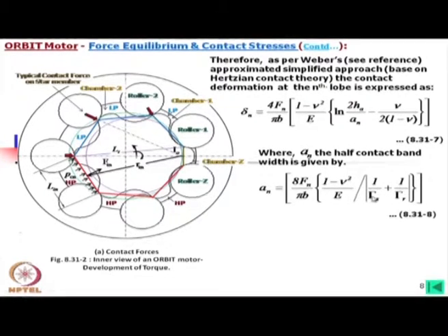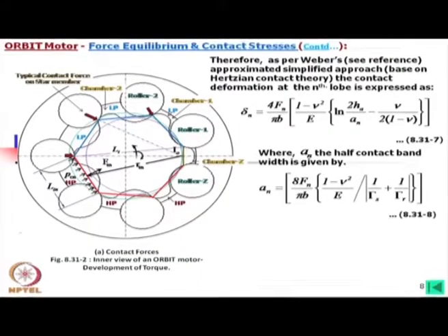Here this is the contact radius of the star and this is the contact radius of the ring, but you should remember this plus sign means both are concave. If you look into the star, it has convex as well as concave. When this is concave, then there will be a minus sign, so you have to take care of that part.